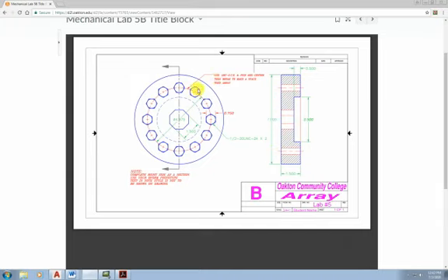And the instructions are specific to pick up certain CAD techniques. There's some information here on the best way to draw the center line that shows the circular pattern by using an arc and then break and then arraying that. And then there's some other information here about which title block to use and how to complete this side view. The drawing is done at 3/4 of an inch equals 1 inch, 3/4 equals 1.